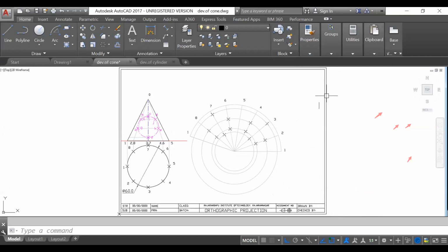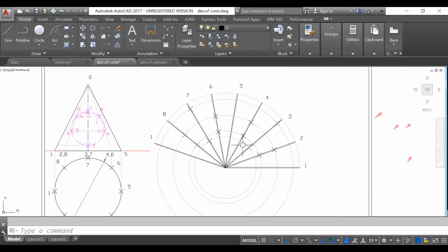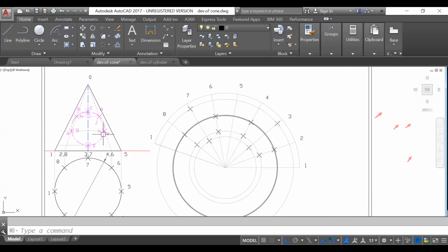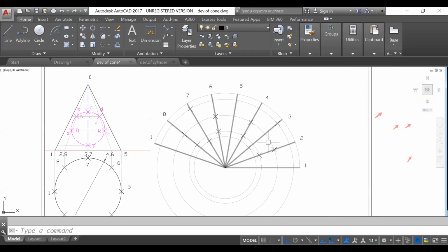But if you observe, the holes are not properly visible here because some of the points on the hole are not uniformly distributed, or cutting points are not considered uniformly. So if you could take one more point here and one more point here, then the accuracy will increase. How to get those extra points I will tell you later on. Before that, I will join as it is.